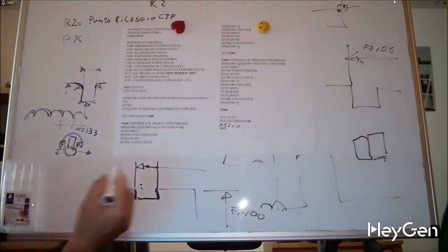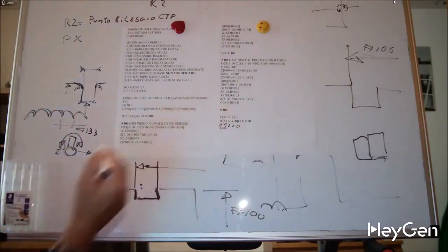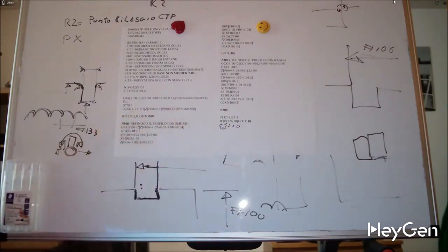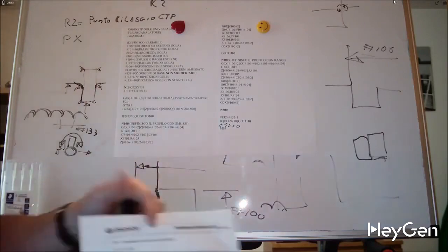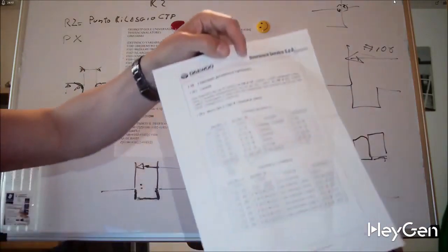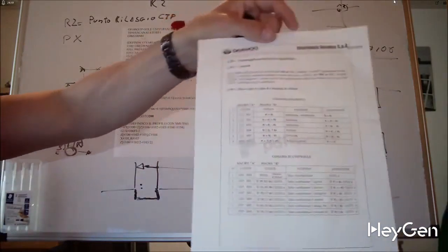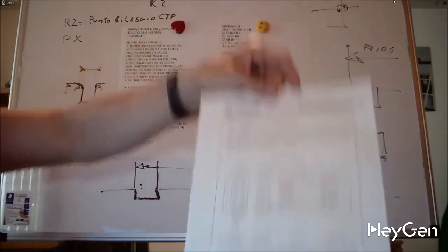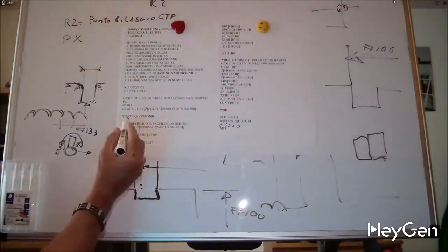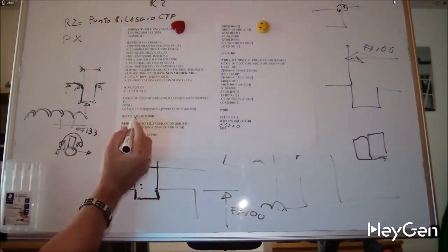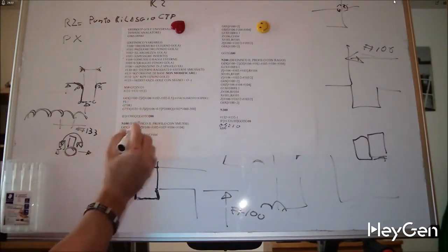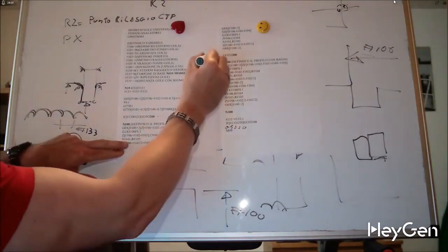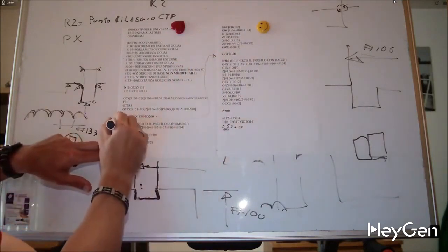So from the moment you enter the thickness of the insert, Q will automatically adjust, according to the table I gave you. I showed it to you before. Go back in the video and print it out. So, if EQ is an equality, if #130 equals 0, I go to N200, so I go here. If it's not equal to 0, I continue.